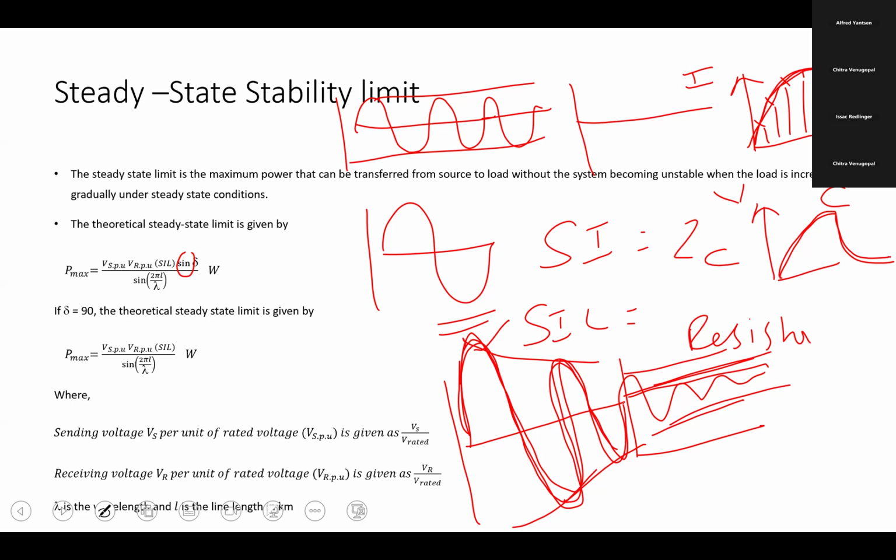At the same time, we also have to look at the peak versus how much it requires. The peak should not exceed the maximum allowable level that the lines can carry. Lines are limiting it. We have designed the lines, the cables, for a particular amount of current. If it goes above that, there are going to be more losses in the line, and lines may also feel loading. So the peak, the time, and everything. We want to see the curve stabilized here.